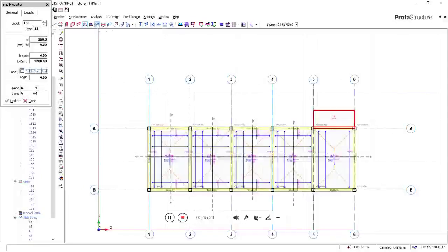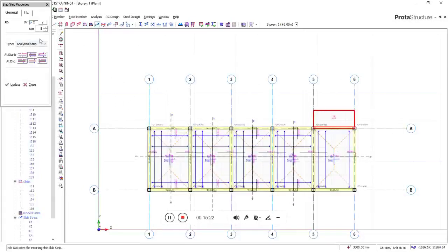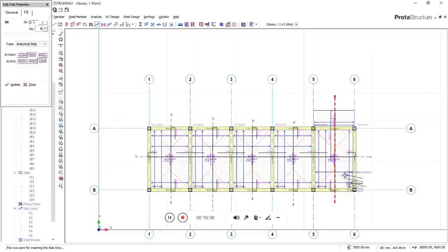So we move again, pick the slab straight. Now at the start of this one, that would be the end of beam, while the end would be cantilever. So I'm starting to draw it from this end. Where you are starting matters. Press your control and then you end it there. So this section is okay.